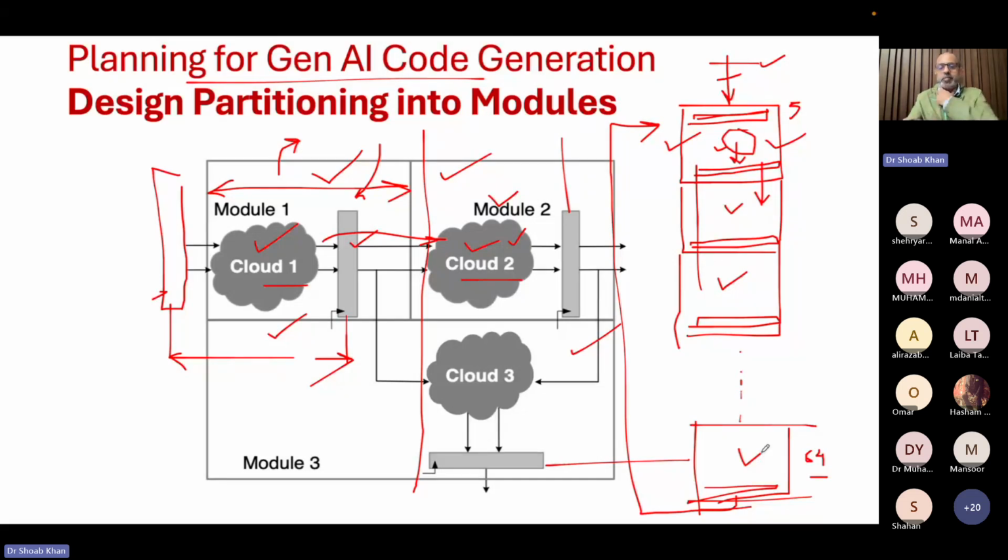These are the kinds of things we will be learning: when unrolling an algorithm makes sense, and when we should not unroll it, and rather take just one loop of the algorithm, convert it into silicon, and reuse it 64 times to get to the final result. So hardware utilization is important, and we need to make sure that we are using our hardware 100% and it is not sitting idle, because we don't want to waste area.